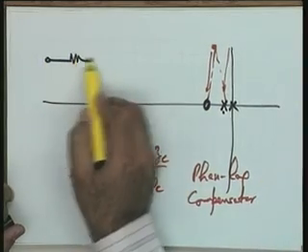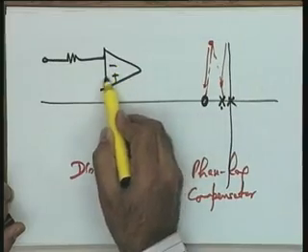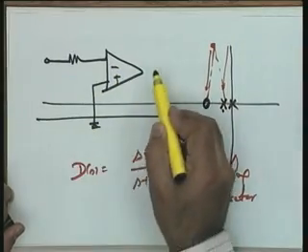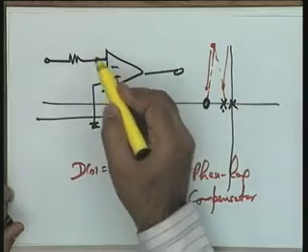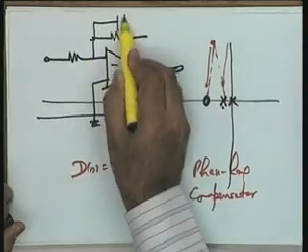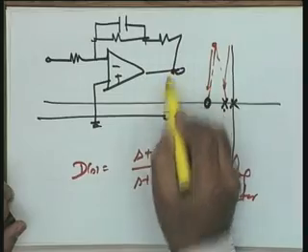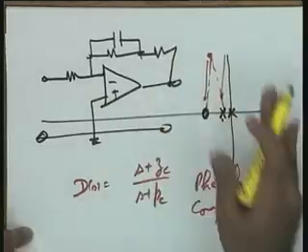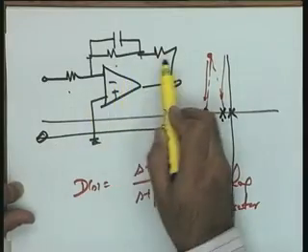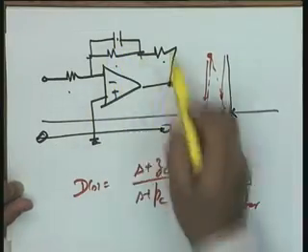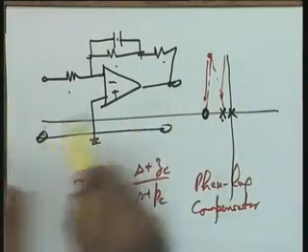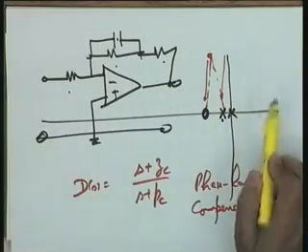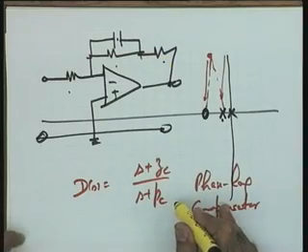The last point, please see, it is for you to check that this system which I am giving you is actually a phase lag controller. Please check this. Make a suitable manipulation of the transfer function of this: a resistor here, a resistor, a capacitor. These are the total elements in the system. Take the input output ratio, make suitable adjustment of the transfer function, and see that it fits into this type of system. I conclude my discussion here, and the next class is going to be two design examples. Thank you.